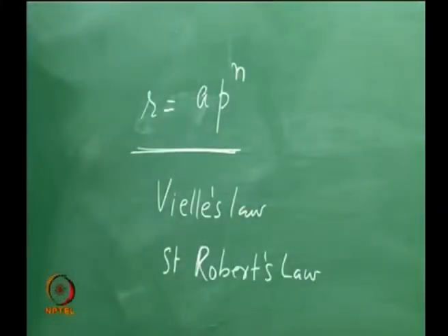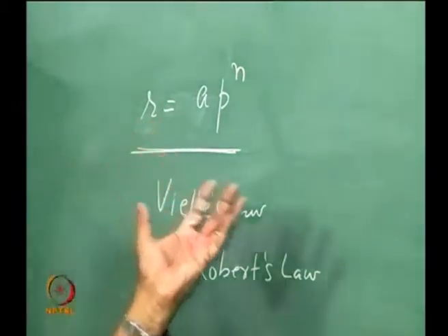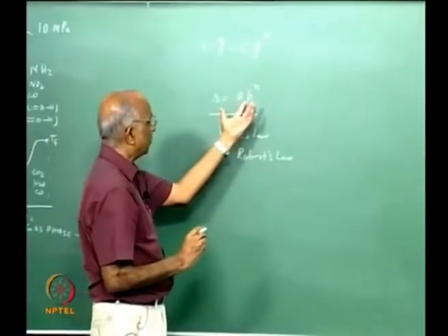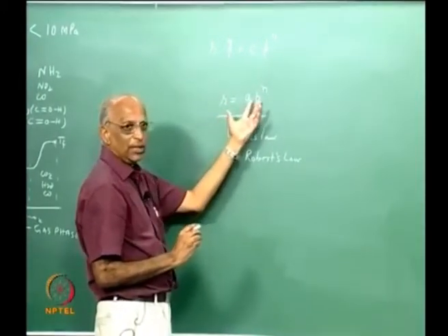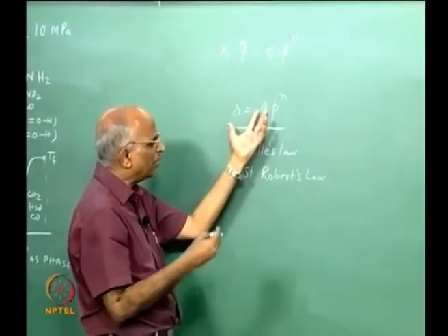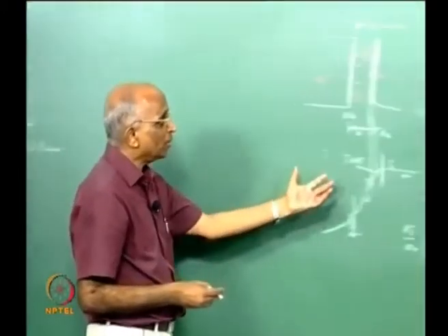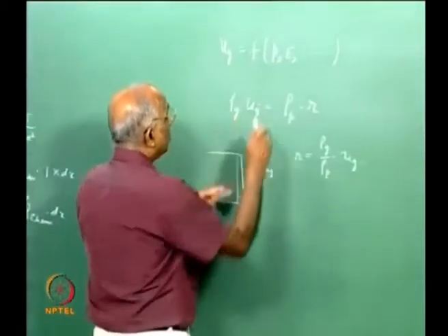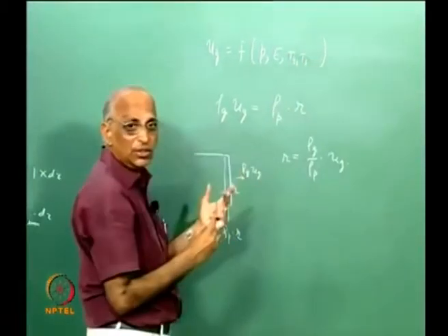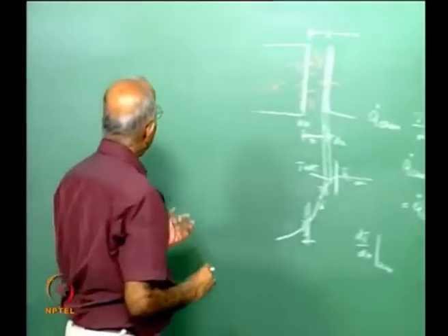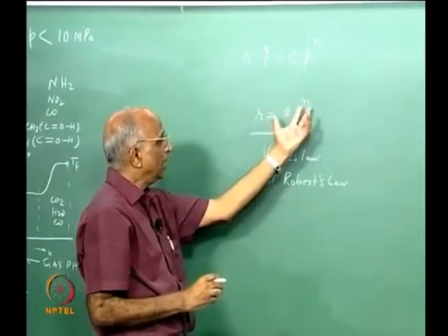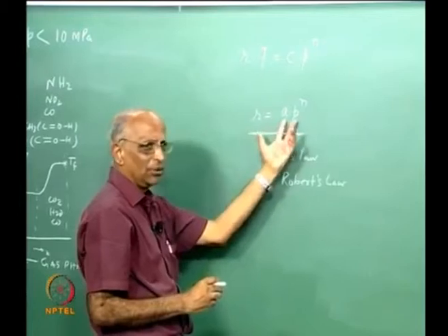Therefore, what is it I have done so far? We said that the surface regression rate of a double base propellant could be written in terms of the ambient pressure P in the form R is equal to A P^n. A will have the compositional features, maybe the initial temperature, maybe the final temperature, because that is also going to be a strong function. Maybe I should have written here Ug is going to be a function of the initial temperature, maybe the temperature T1 and so on, these are all important things. Therefore, I put all the effects other than pressure into this A factor here, that is the pre-exponent, and I have the burn rate law giving R is equal to A P^n.